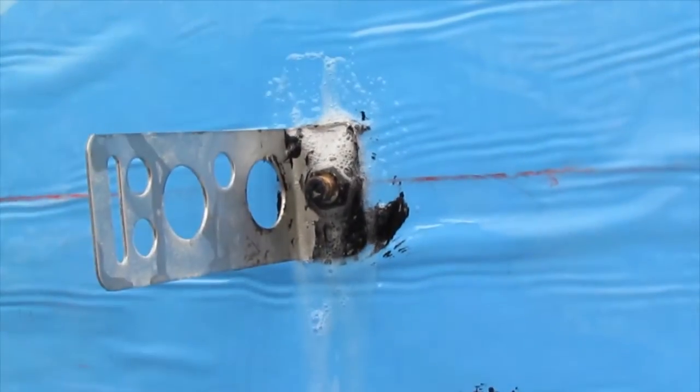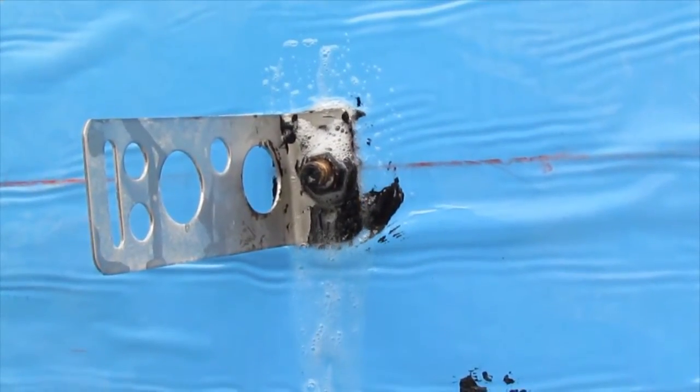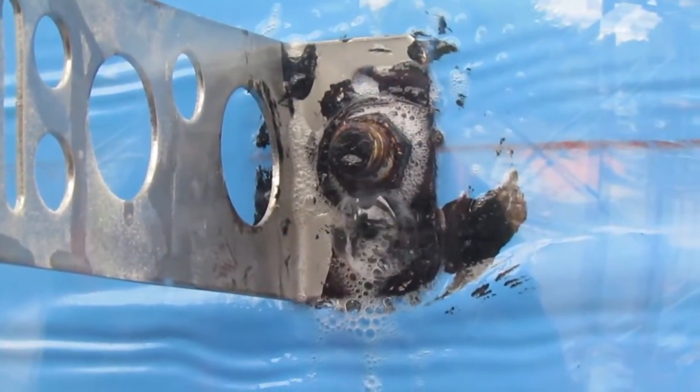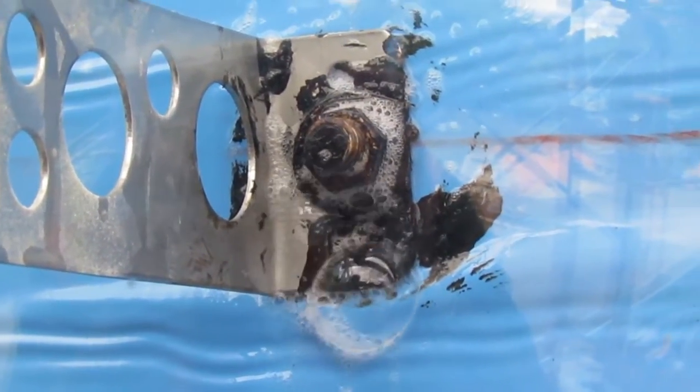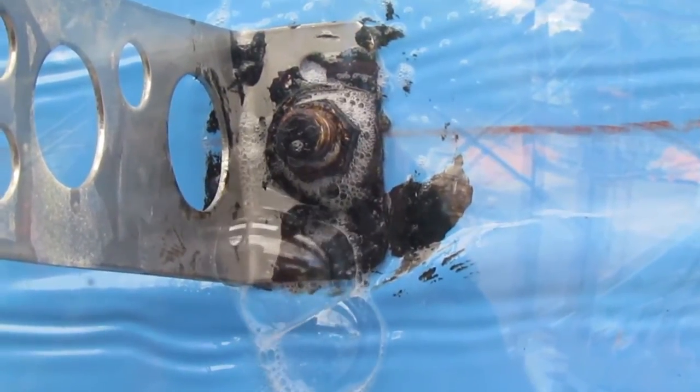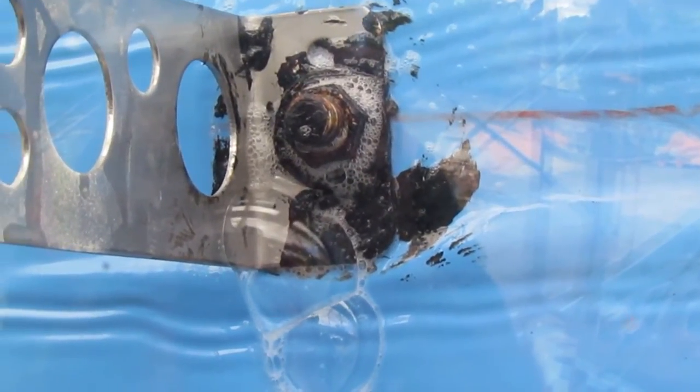In order to use the detector, a surfactant is first applied to the area being tested. A dome is placed over it and a pressure differential is created, drawing air through the leak or deficiency to show the bubbles form, as you see here.